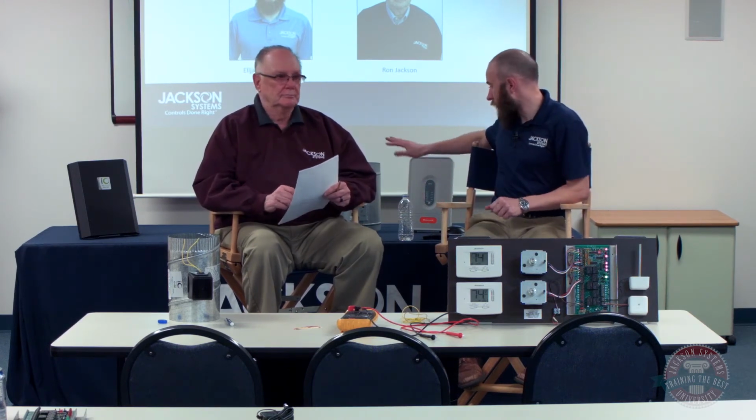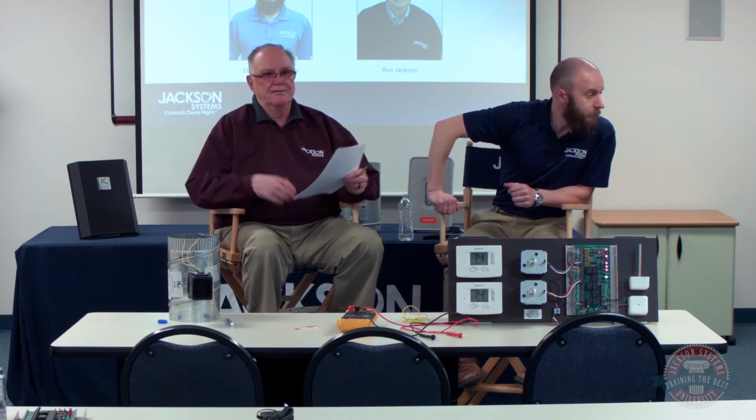3-wire motors typically are a lot more efficient. The Belimo 3-wire actuators are fantastic. They're phenomenally reliable. They're really efficient. They're quiet. They're great motors. And if the damper's a little warped because somebody stood on it, they have more torque, so that motor's powerful enough. You're not gonna stall the motor. Most 2-wire motors, since they're spring return, it's not easy to stall them, but it's a lot easier than, well, typically the 3-wire motor has 5 times the torque of a 2-wire motor.